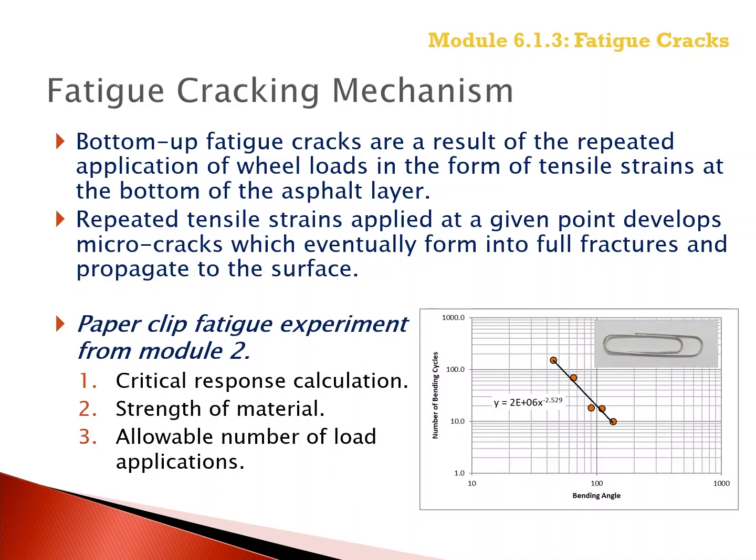Remember the paperclip experiment from Module 2, where we failed the paperclip with multiple bends of the paperclip. In concept, the fatigue failure or cracking of asphalt layers is no different than that for the paperclip or for Portland cement concrete that we discussed in Module 5.